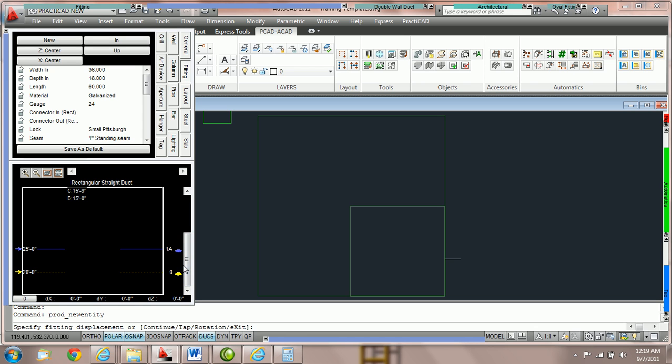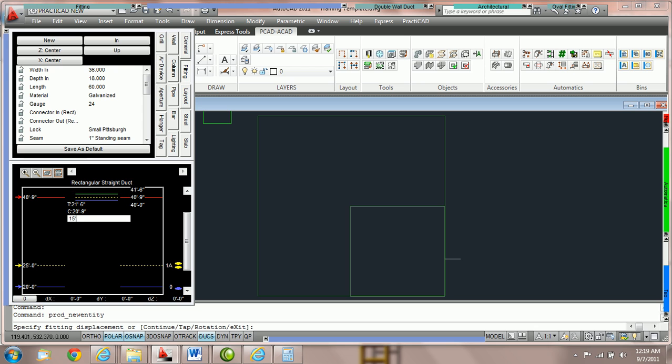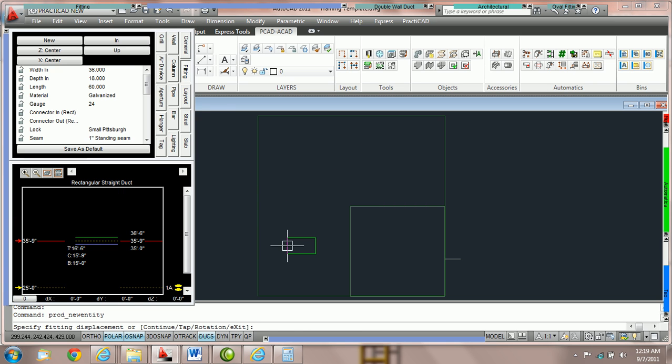So we're going to change the 20 foot back to relative bottom. We come here, click on our yellow button, and that'll switch it to blue, or relative bottom. Once again, I like to use the elevation marks view because it centers everything and makes it easy to scroll through my elevation box. Now let's put bottom at 15 foot. That just means 15 foot above this slab here that we've got marked. I'm going to hit enter, and draw a duct running from left to right on the screen,